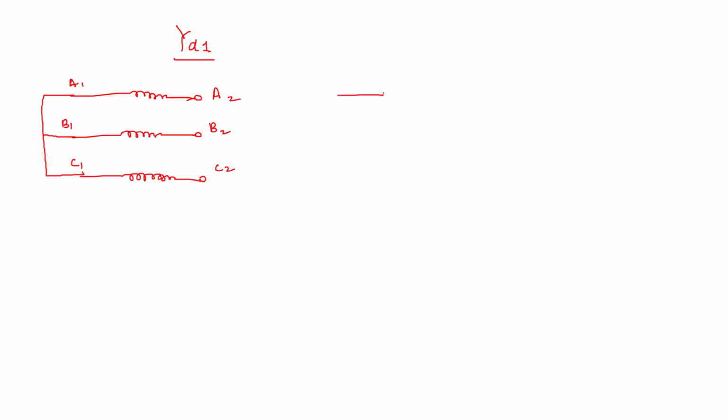Now here I am drawing the delta winding part, but I'm not connecting it because I do not know in what way to connect. Okay, it's like this. So how to connect my delta winding depending on this vector group? So let us see. First of all, this is my HV. This is the LV. It is at 1 o'clock position. So this is 30 degree. Okay, this we have seen in the beginning of the class.